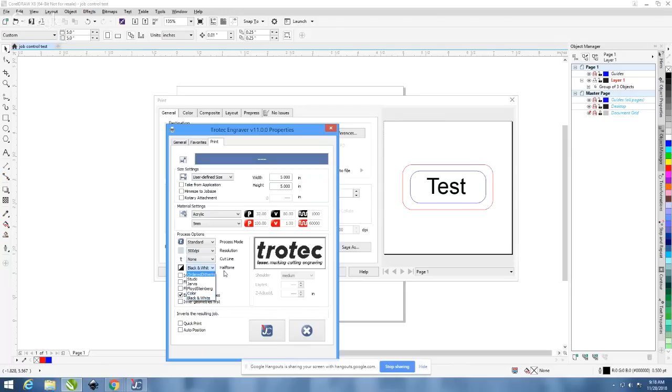John, I guess the invert you'd really use if you're engraving any black acrylic or granite, like a photo engraving, you'll have to invert the colors, right? That's really what it's basically there for. Exactly, yeah. So on a piece of black marble, for instance, the engraving is white. So you actually will want to invert your image so that the areas that turn out white on the piece are the areas that are actually black in your engraving. So that's why you would want to invert it.